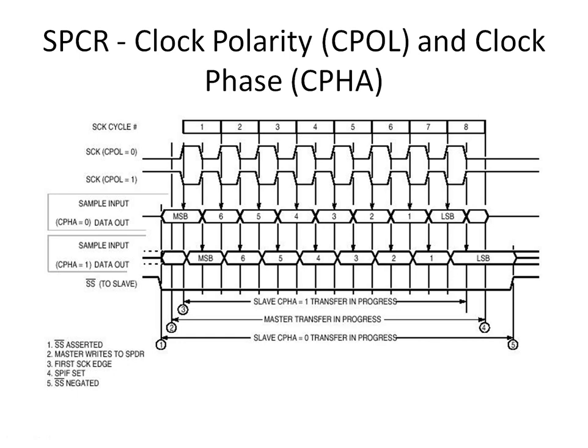One of the things that we need to do is look at the receiving end. What are we sending the information to, and when is it going to be able to accept data? When is it going to take the data in, on what part of the clock? Once we know how the receiving end is taking in data, then we can properly set up the CPOL and the CPHA.